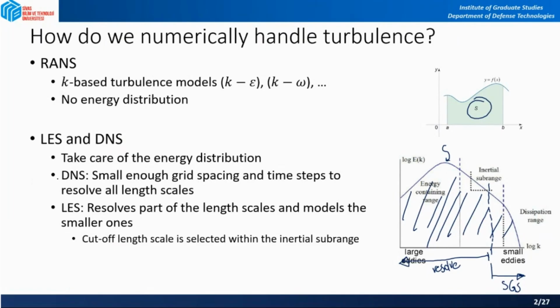If the flow is simple enough, like a simple pipe flow, it will not be that bad. But if you are dealing, for example, with a multi-stage compressor, with all kinds of rotors and stators interacting with each other, then it will be problematic, because you're oversimplifying a complex flow by just ignoring the physics of the flow.